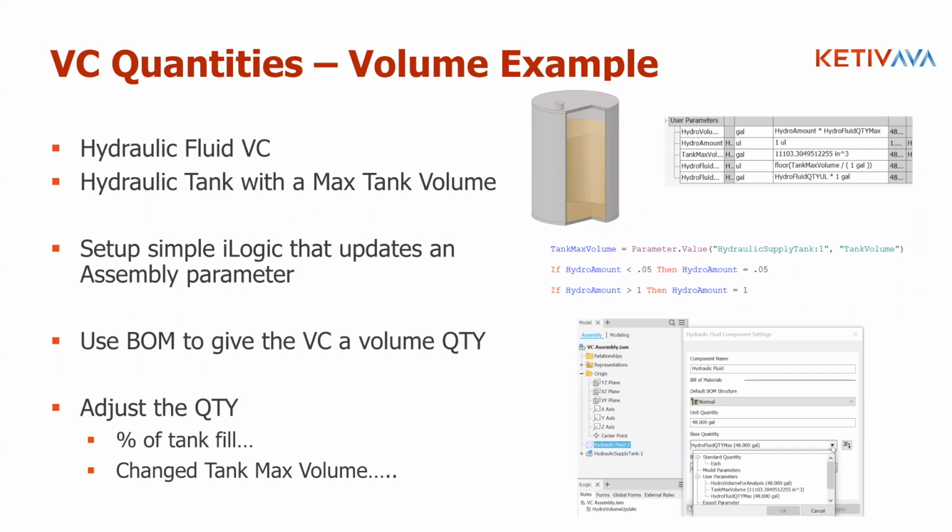Yeah, there is actually. Jim had a kind of follow-up question regarding the reuse of the virtual components. Do you have to open up essentially the assembly or wherever those virtual components are to copy and paste them over? Or is there a way, can you get that information another way? Out of the box with Inventor, yes, you have to open the assembly file that they live in to start the copy. With the Inventor API, you might be able to do other things, but I'd have to look into it. I haven't given it that much thought before.